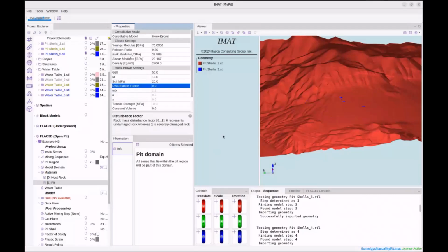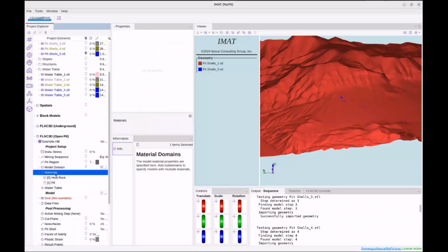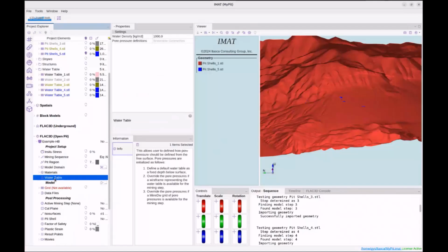Great. So I've just defined my two material properties. And then the final step in our workflow is to define basically, well, the water density. And for this example, we can just leave it default. We don't want to change the fluid density of our materials. Note that when we created the FLAC3D project, if we chose the option depth below surface or fixed elevation for our water table, those elevation properties would become available here, where you can override those and choose those elevations or distance below surface.